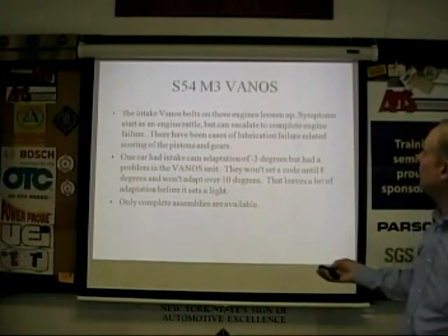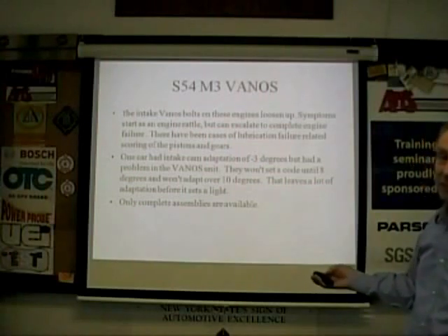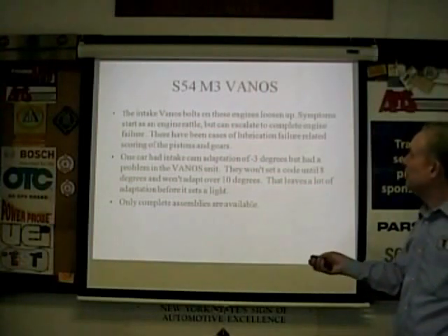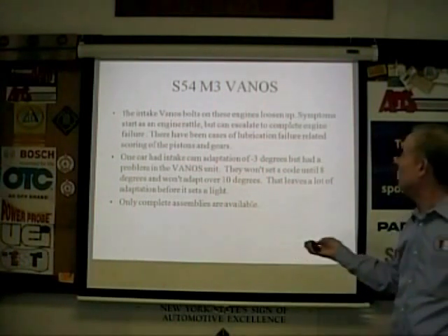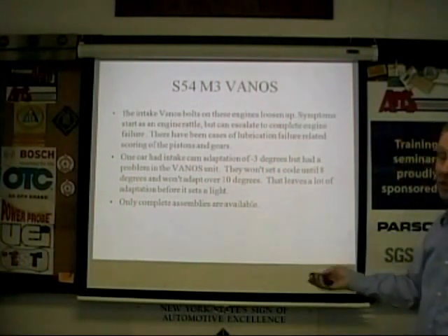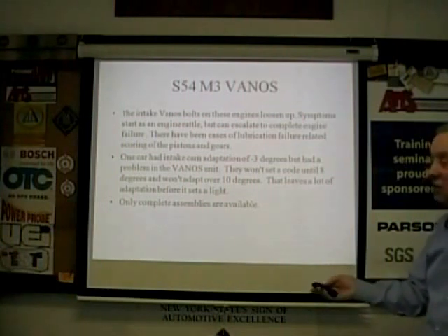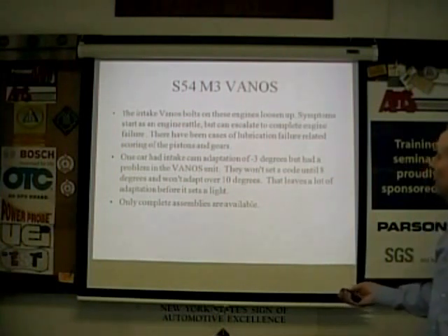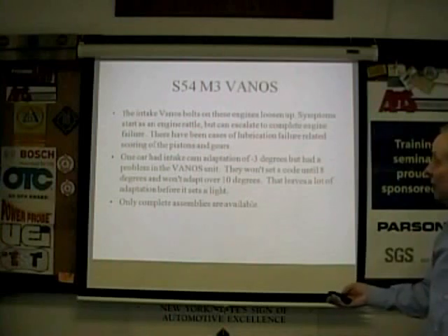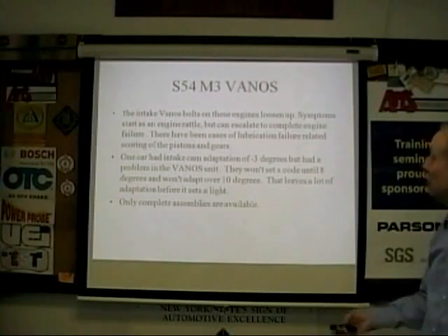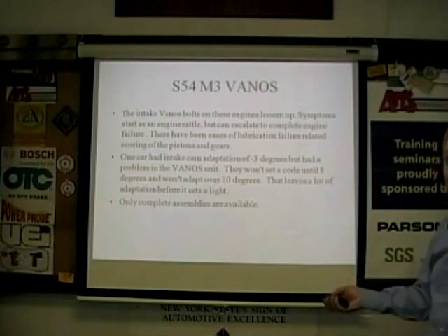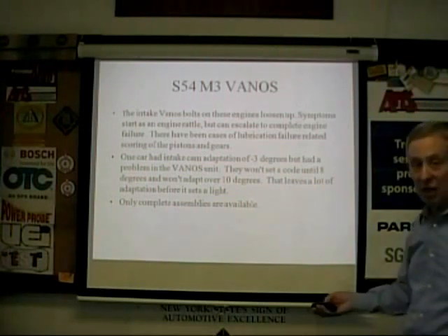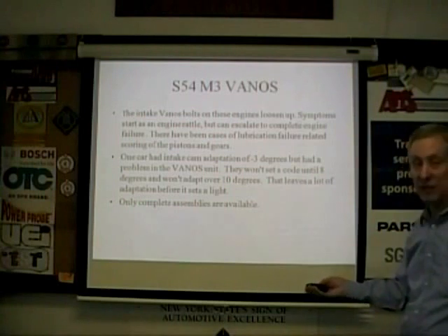The thing to understand here is, again, it's got special oil, 10W60. You can get some engine rattling, you can get noises in this particular one, and it can escalate to complete engine failure, especially considering how these cars are driven. Really it's recommended you use the right oil. You also have to be careful about when you draw the line on the Vanos. Vanos does not have serviceable parts. You have to change the whole thing. It's very expensive. It's over $2 grand.